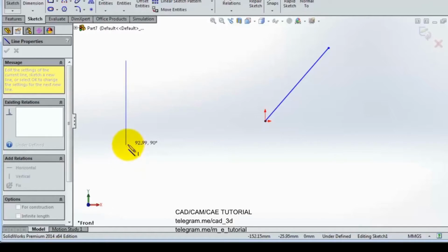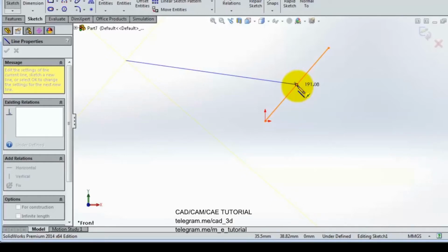So another thing to use with the line, let's select the line, pick the point where we want, and if you notice this yellow relation appears to you, that means this line is vertical. So when you are drawing, you have some relations as well. For example, now if you hover over this line, you are able to select the middle point, and you see the relation appear next to that, telling you that it is a middle point. So we can pick it.